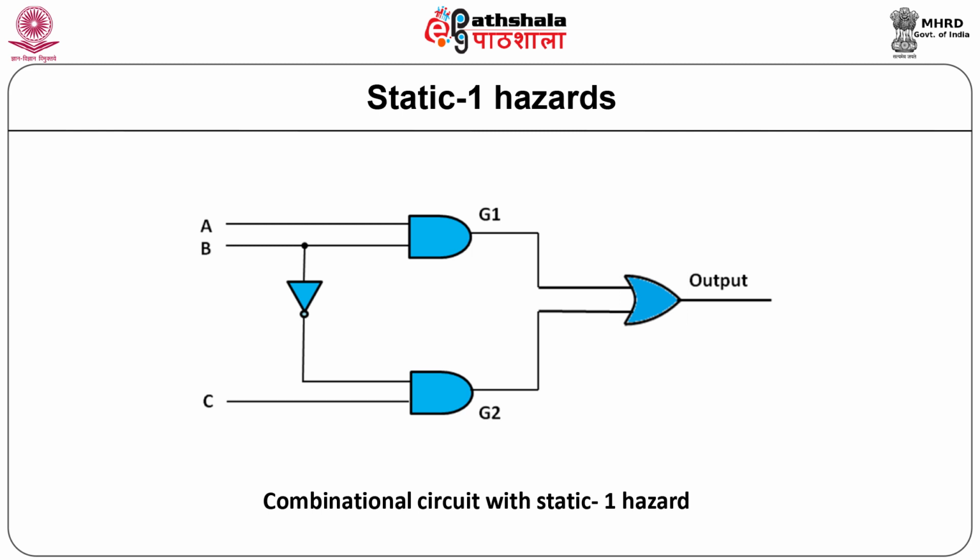Let us now study the hazards in any combinational circuit in general. To demonstrate the hazards in general combinational circuit, let us consider the circuit as shown here. The circuit consists of 3 AND gates, a NOT gate along with their interconnections. This figure also indicates the waveforms at various points in the circuit and the glitch generated at the output.